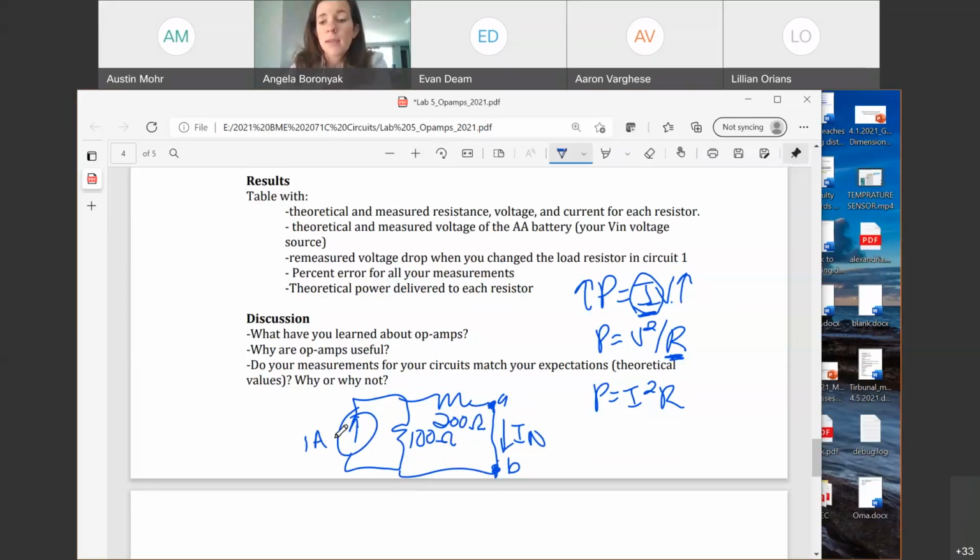Good, they're in parallel. Again, they don't look geometrically in parallel, but circuits-wise parallel, right? Means have the same voltage drop. On one side, they're connected at the same point. The other side, now that this is wire, is the same point. If I have two resistors in parallel, what was our shortcut for finding the current through one of them?